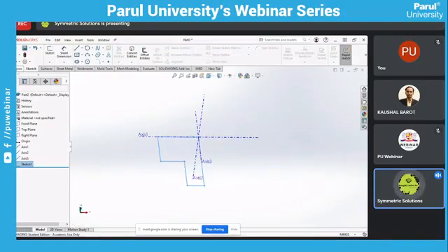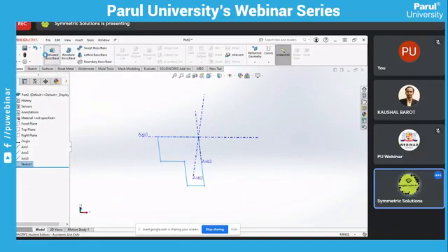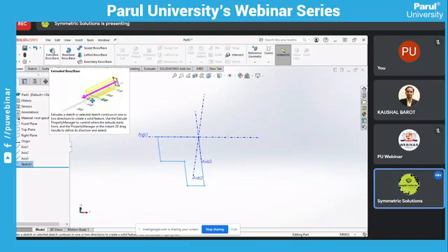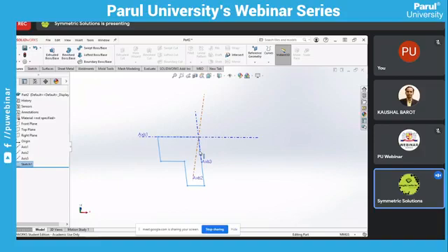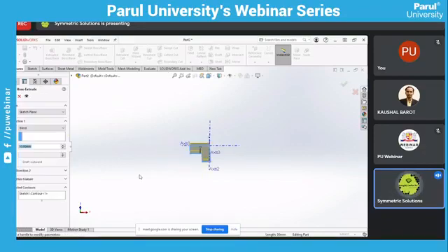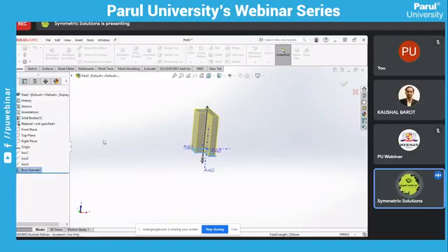I'm giving some 3D extrusion. So we have the extrude feature. The basic feature is extrude. Extrude is to give the Z direction, to give height to your 2D drawing. If we have a 2D drawing like this, and we have to apply a third direction in a straight, linear direction, then we apply the extrude feature, select this drawing, and give the height here as 150, then give OK.